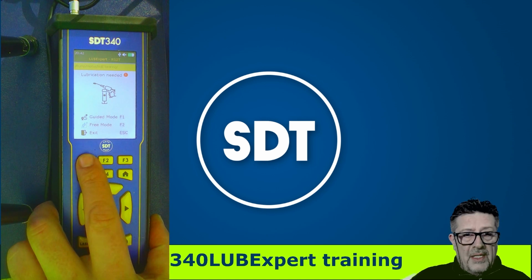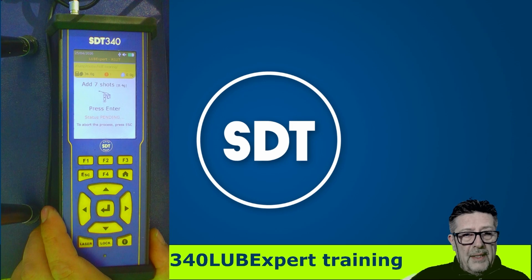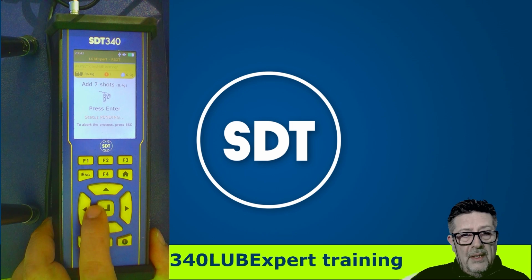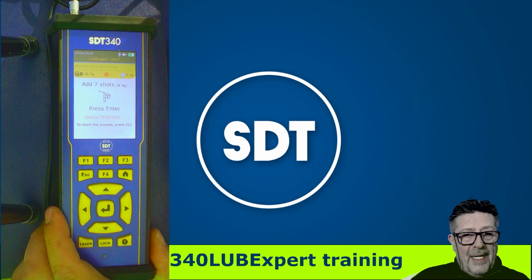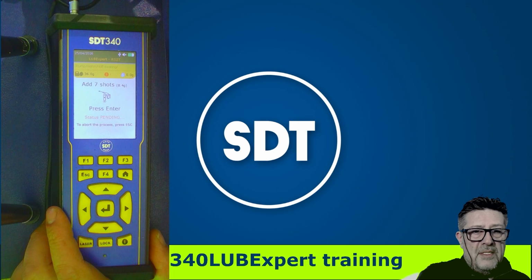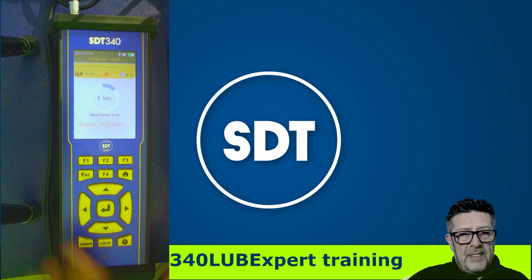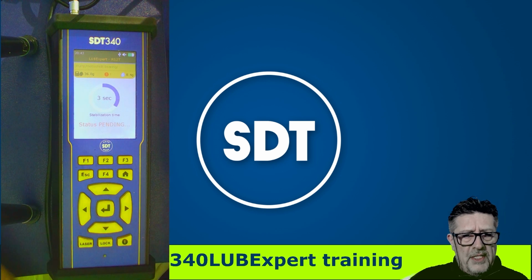First, now let's choose the guided mode. Guided mode will completely guide me through the process. And as you can see right now, I can see the zero grease is added. And I'm instructed to add 7 shots of grease and press enter. I can press escape and exit the process at any moment in case of the emergency that we will discuss later. So right now, let me put 7 shots. I'm working on a simulator, so I just press 1 button, not 7. And I press enter. Now we are in a stabilization time.